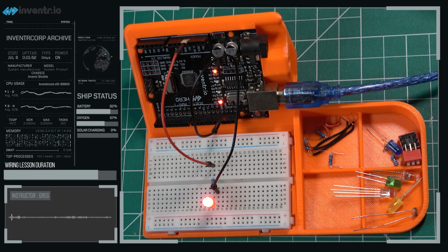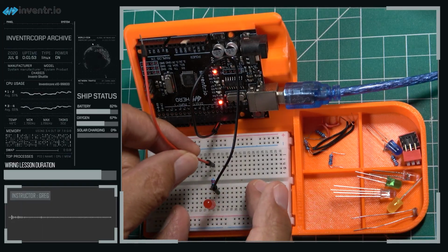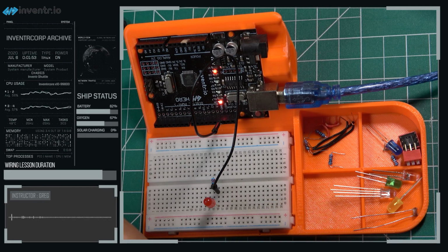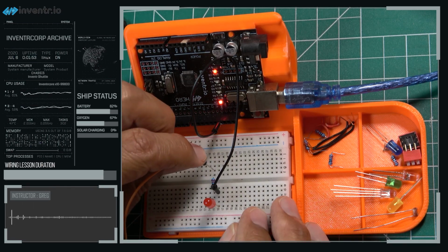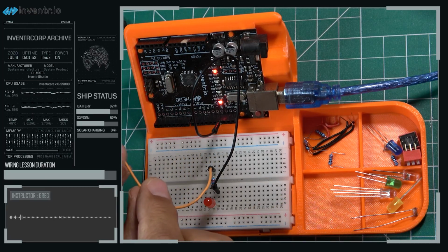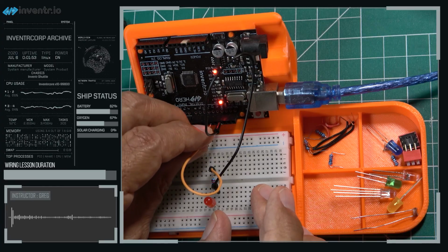It's tempting at this point to just go ahead and take our red wire and use that to connect over here to pin 12, but that really wouldn't conform with our practice of using red wires only for the fixed 5-volt supply. So we're going to be a little bit more careful about things here. So I'm going to disconnect the red wire and actually remove it. And instead I'm going to use a different colored wire. In this case I'll use an orange wire, and I'm going to make the connection between the positive side of our LED and the current limiting resistor, and over here to pin 12. So that's pin 12 right there. We'll plug it in.